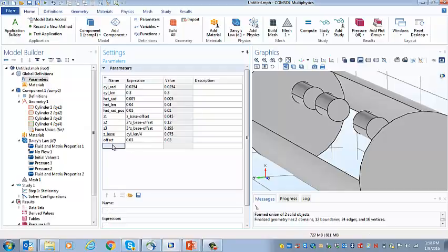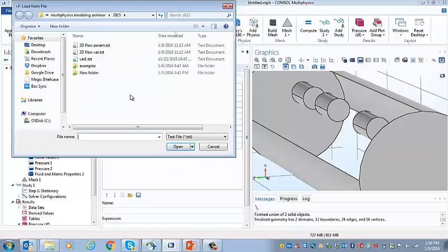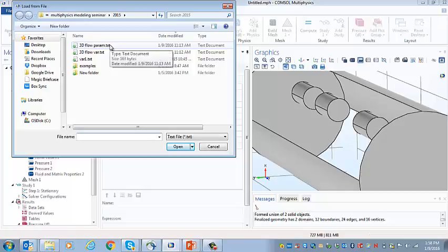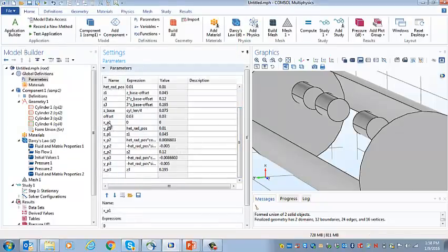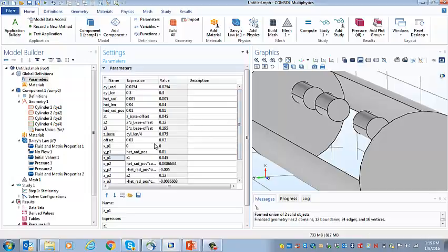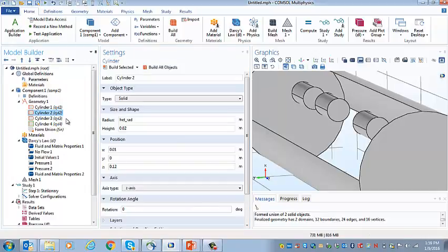So in addition to this, I've got another file that I call flow variables. I'm going to open that up, and this has the lines from here to here, and that's x p1, y p1, z p1. This is the x, y, z location of the p1 cylinder. Okay, so this set of variables I use to set up the locations of the 3 different cylinders.